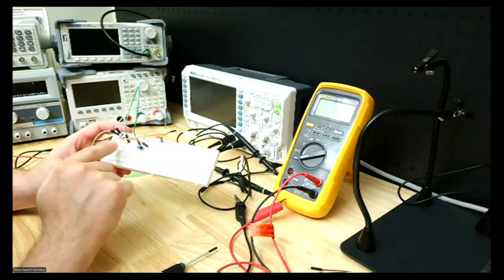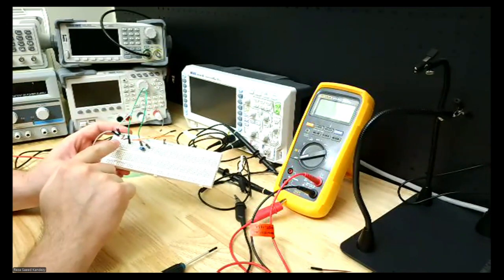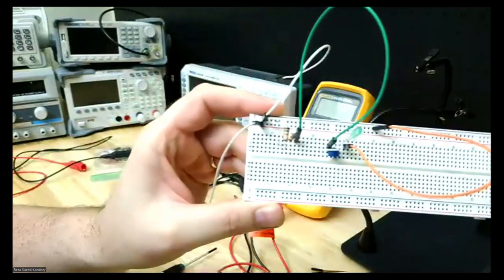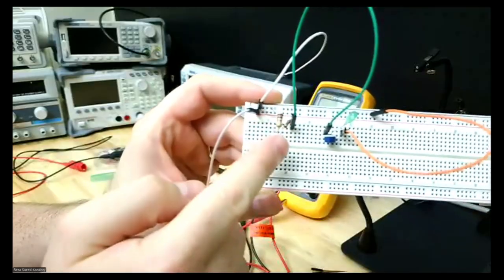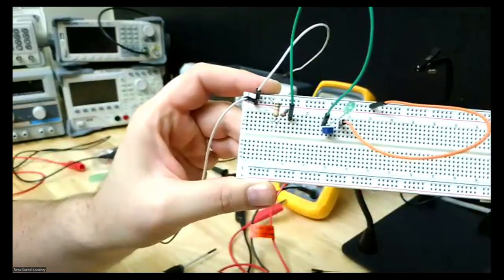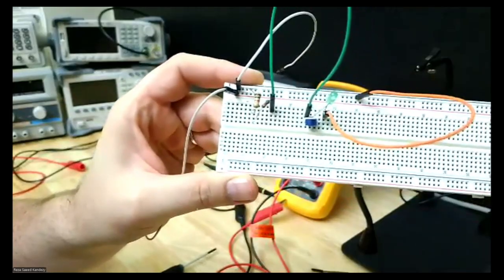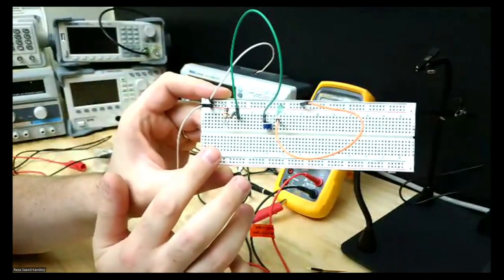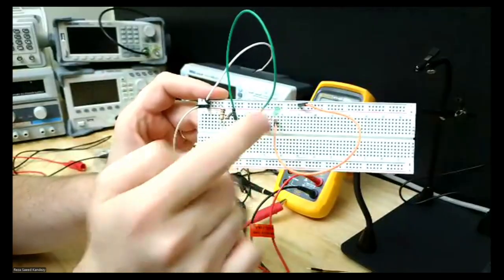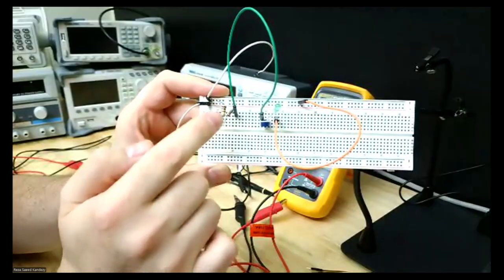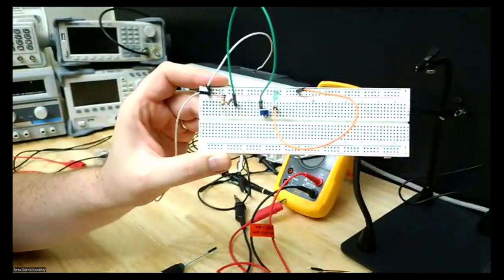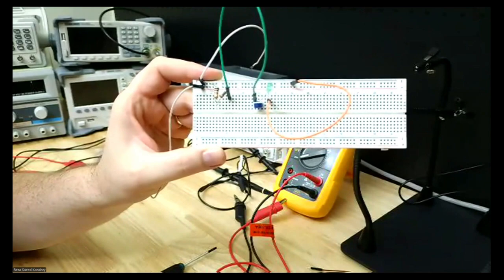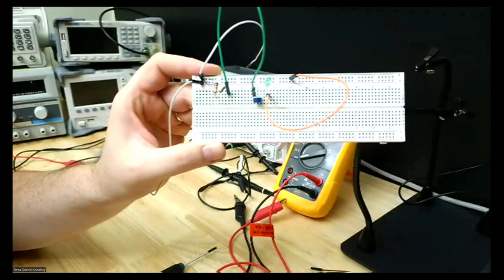We have a 1.5K resistance. I didn't have 1.5K, so I used, as you can see, two resistors, 1 kilo ohm and 500 ohm in series, so I could create that 1.5 kilo ohm. That was the safe resistance for our LED. If you don't have these values, it's better to go higher than lower. We wanted to make sure that our current does not exceed the maximum current that we intended.